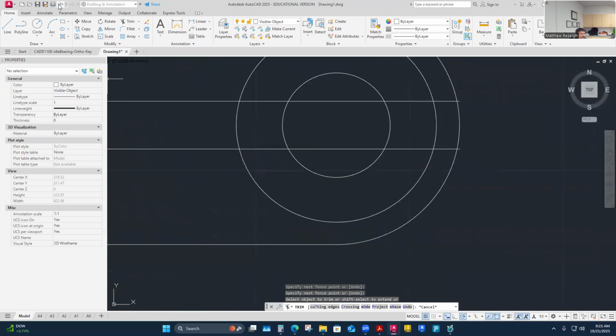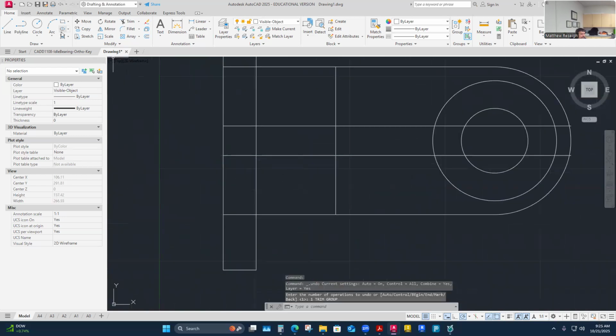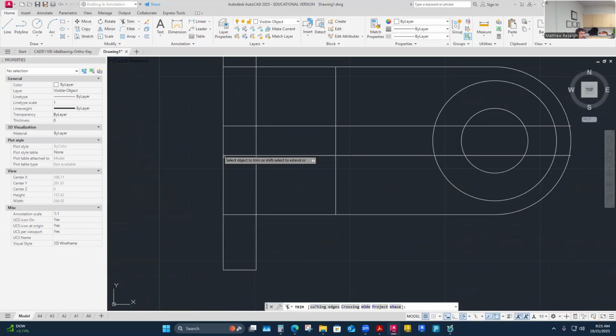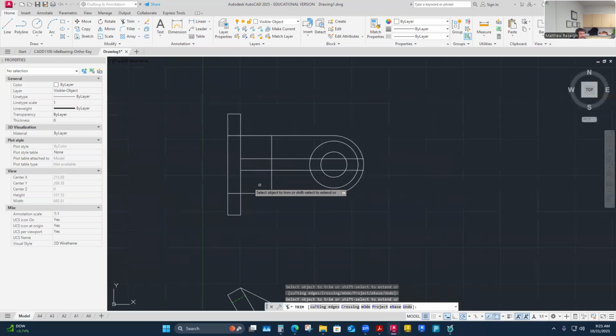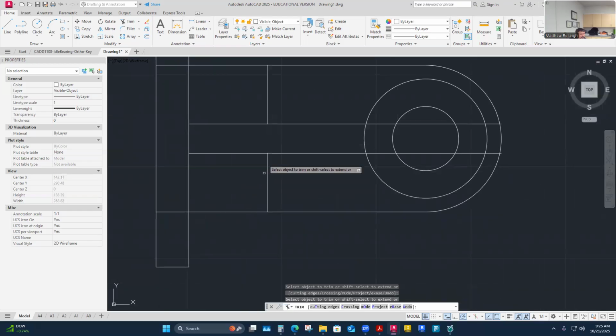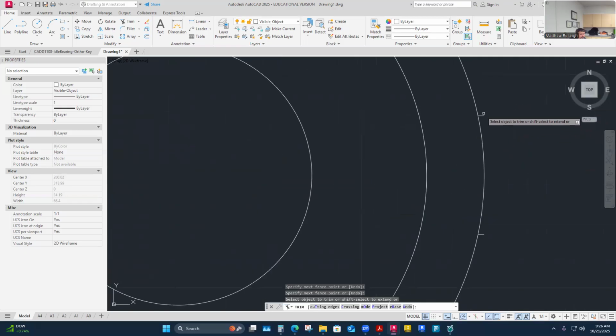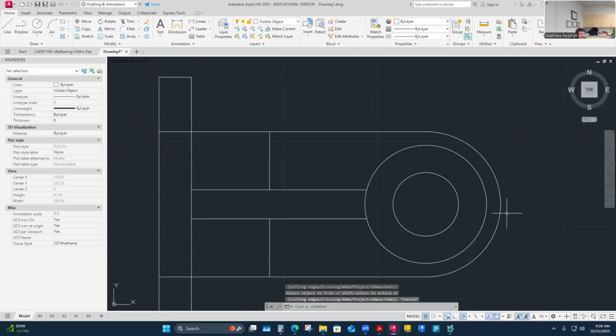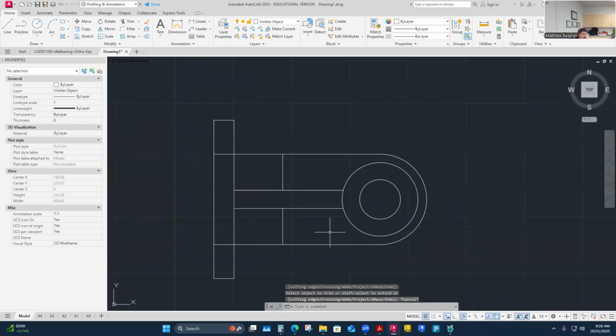Well, that wasn't exactly how I wanted that. Come back one here. Trim. Do you want this one trimmed? It stops right there. I shouldn't see the bend across that. And then I think it's just how I had that selected, the way I trimmed it, it kind of trimmed it like that. Okay, so that should be top down looking at my gusset now.